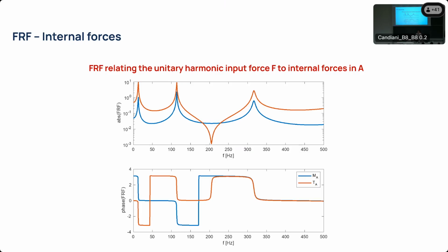And if you want to dimension those elements in your code, or because maybe one day you will go out and be engineers and design bridges, you will have to take into account that at some frequencies, even if nominally the bridge should be able to hold all the weight without problems, we might have an amplification of the internal action, which is so high that then you have failure, which is not something I like you to discover. So remember that you can use this framework to look at the various effects of external actions onto the internal forces that our structure experiences.